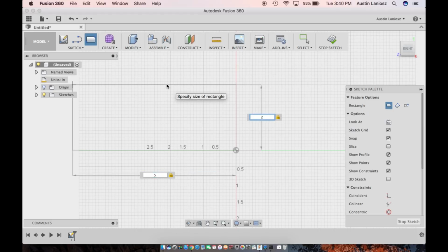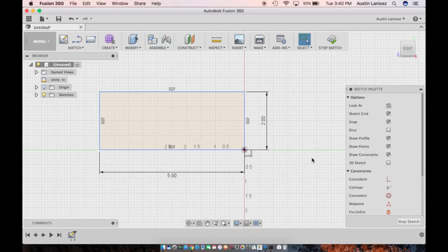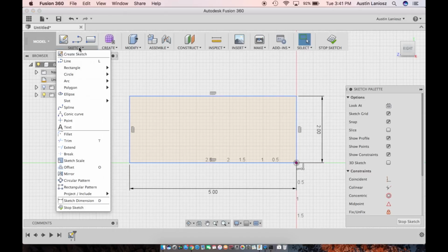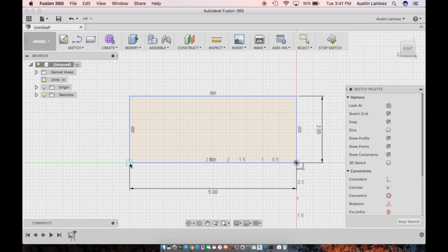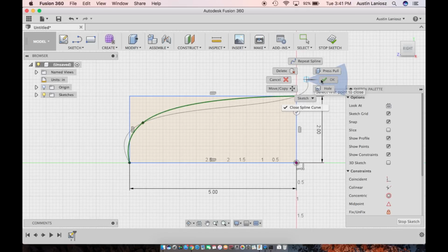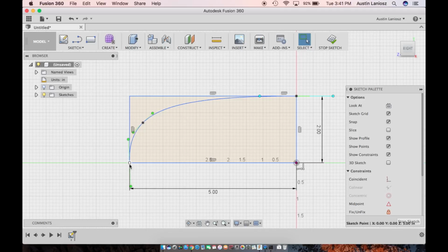And then I'm going to create a spline. That spline is going to run through the X and Y of one side of the box to the other. So I want to create a point, place down the other one, right click OK. Now these little anchors I'm going to make directly up and down, so they're constrained to the X and constrained to the Y. Then this point I can just play around with and mess with the curve.